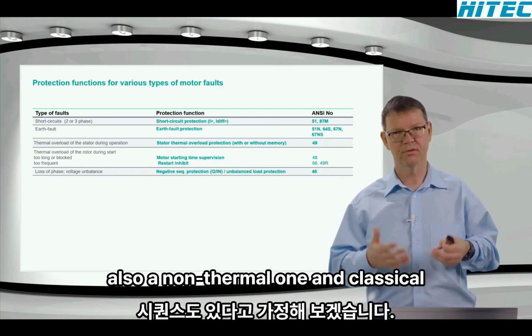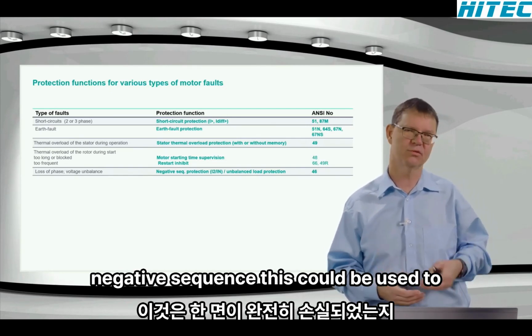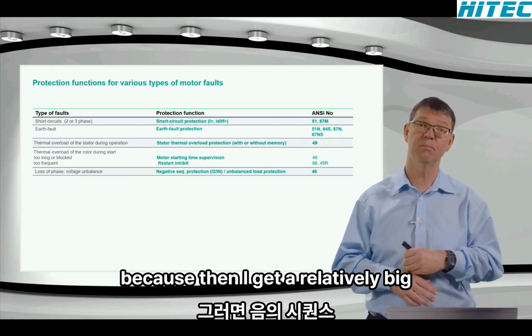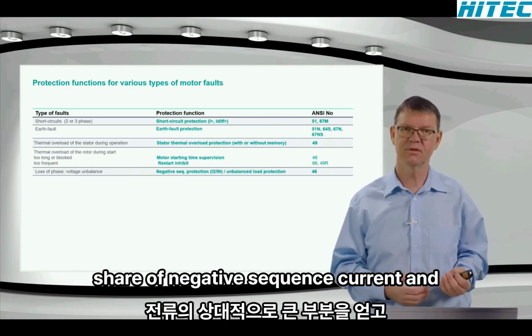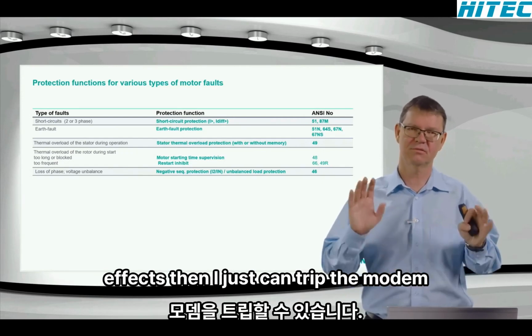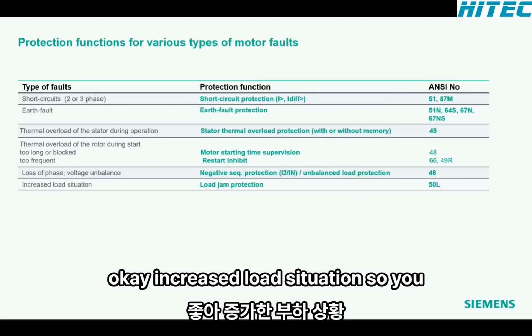Of course, we also have a non-thermal one, a classical negative sequence. This could be used to detect if one phase is completely lost, because then I get a relatively big share of negative sequence current, and then I don't need to think about thermal effects, then I can just trip the motor. Okay, increased load situation.